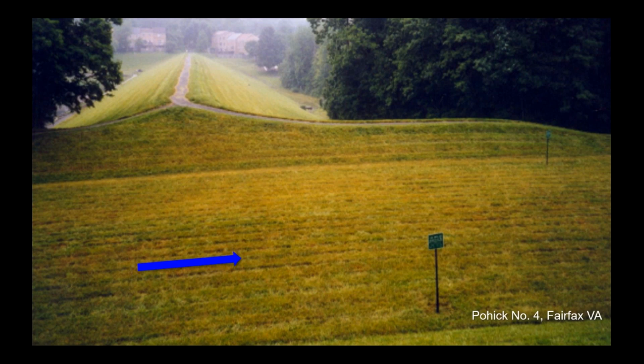So here we have a grass-lined spillway, and you can see the embankment in the background. And in order to prevent the spillway flows from going down the groin of the dam, you'll often have a spillway training dike. So that's a very important feature of an auxiliary spillway, because it contains the flow within the spillway and allows it to discharge safely away from the dam embankment.